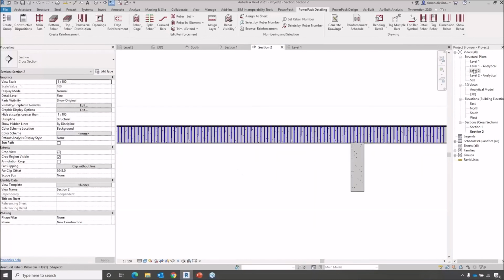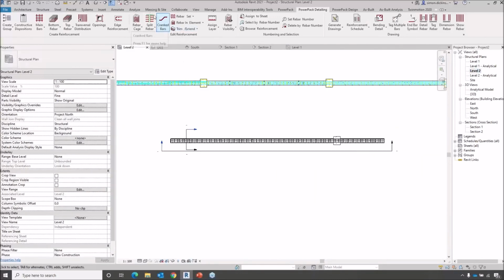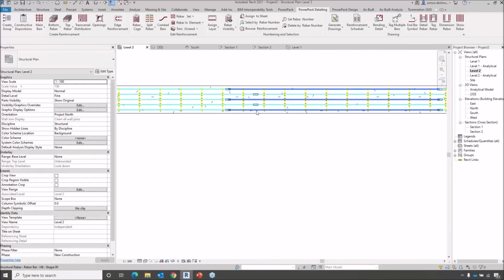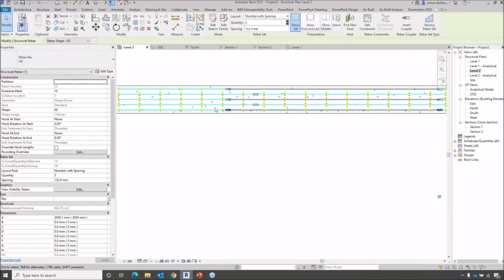So the split tools are really, really clever. I particularly like that they are so intuitive in the way that they move. Very, very powerful set of tools, and they save an awful lot of time. One of the things you've got to remember with the way that Revit works is that it's a single rebar set. It's very, very hard to break that set using the Revit tools to be able to stagger that information. Our tool automatically changed that into these different sets and split them down.